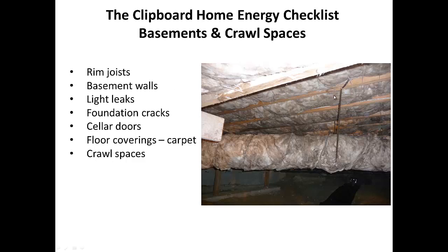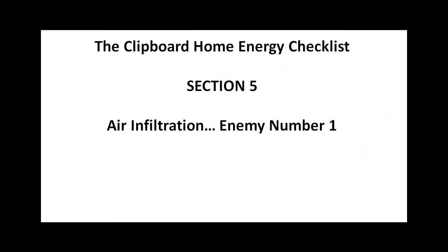So whenever you can, you may need to take some of those copper pipes and move them up into the cavity and then put the insulation over top of it. So just be aware that you can cause a problem by doing something good. You can cause a problem with your pipes if you insulate and don't protect the pipes that are in there.